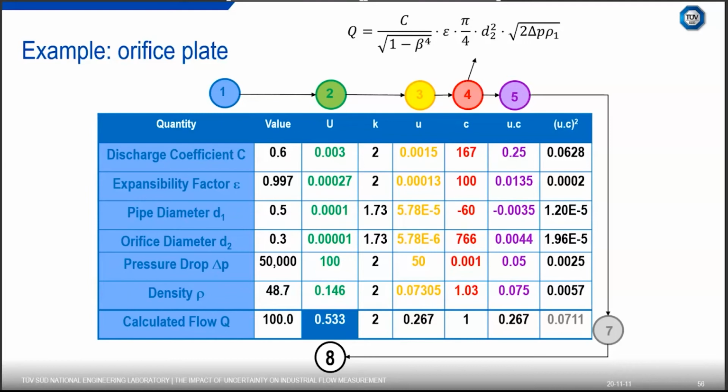So one method you could think of doing this, you've got all our uncertainty values, you could quite simply add all of these numbers together and get an overall uncertainty. However, this value would tend to be larger than would be realistic, because it's not realistic that all of the values are going to be out significantly all of the time. So we need to take that into account. So the typical method to assess this is we use the root sum of squares method for uncorrelated measurements.